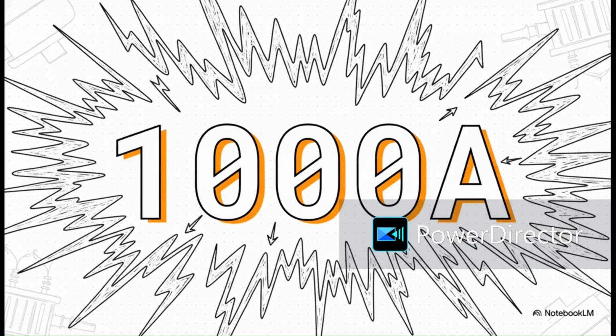Now, wait a second. Earlier, we said the restraining coil blocks current. So why doesn't it just block those 8 amps? Well, in reality, a true internal short circuit doesn't just create an 8 amp difference. It violently spikes to hundreds or even thousands of amps, like the massive 1,000 amp figure we're talking about right here. This physical reality is the key to contrasting an actual fault against those minor magnetizing inrush currents. The coil distinguishes between them purely by the sheer overwhelming magnitude of a true fault.